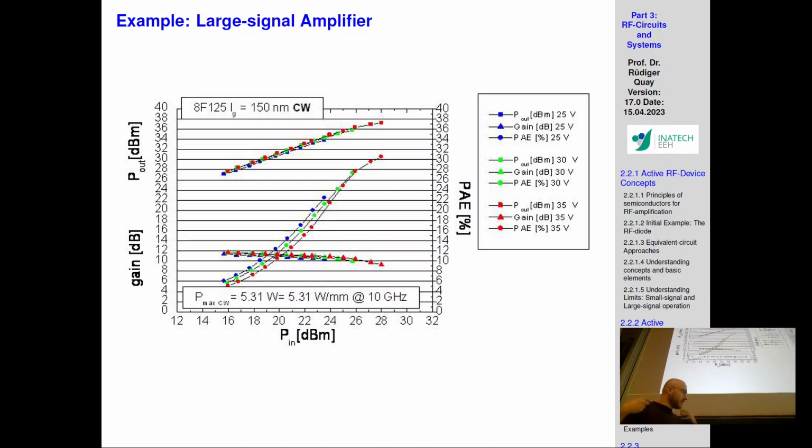So you have an amplifier which you want to amplify 16 dBm into 28 dBm, so let's say 10 dB difference. You want the device to give you this 10 dB difference, but at the same time, your device is working with 2% of efficiency. So it means that 98% of the power that you're giving is getting lost. That is insane. You can't operate the device like that because it will start to burn.